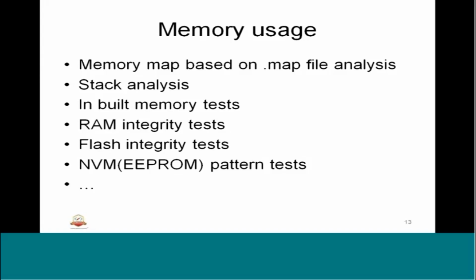So basically, the RAM, memory, and flash will be checked with the help of integrity tests. Integrity tests could be walking ones or pattern tests. NVM also will be tested with the help of pattern tests or walking ones tests, where the DTC prompts are used for fault recording and storage.